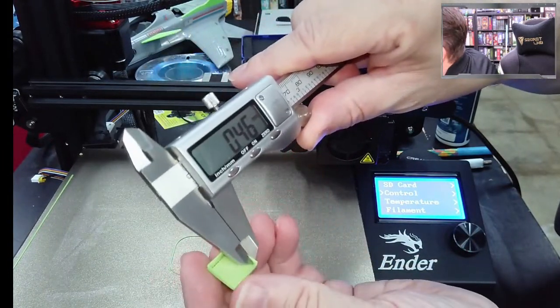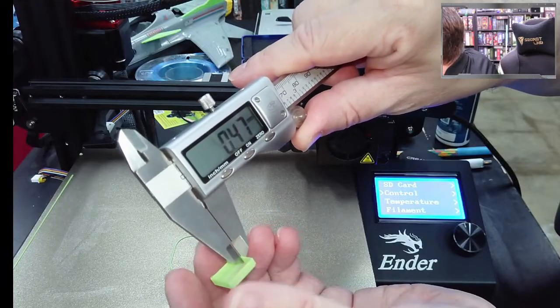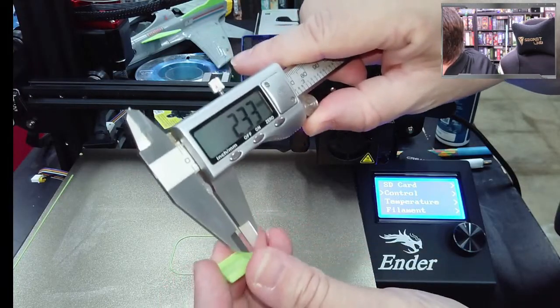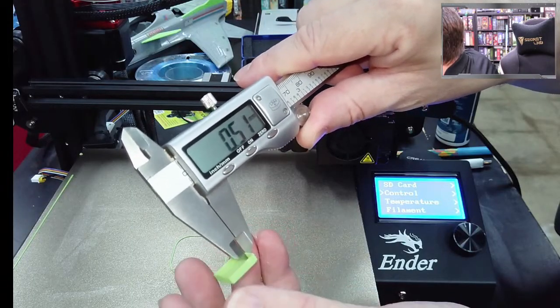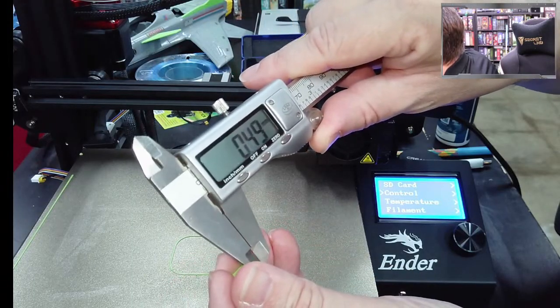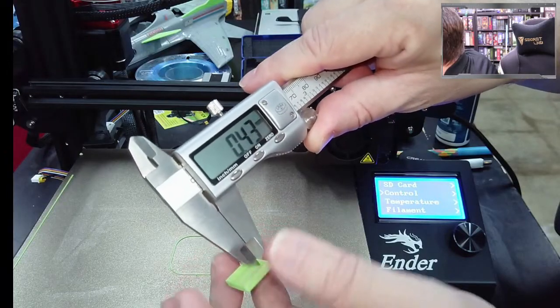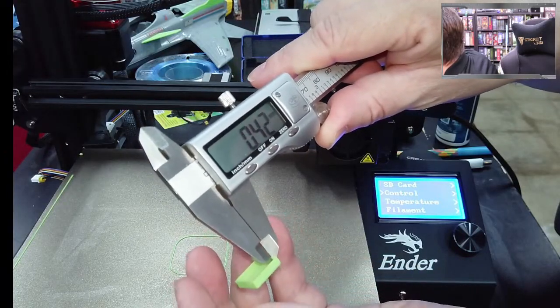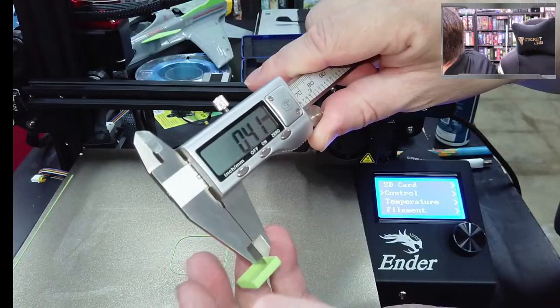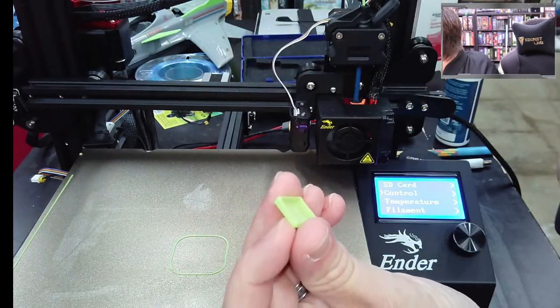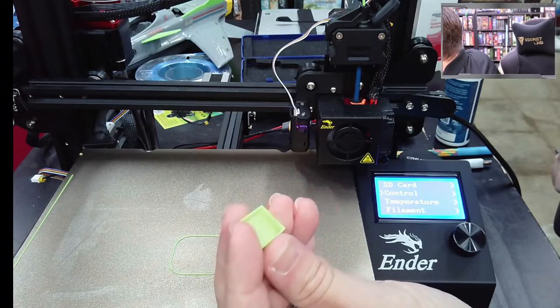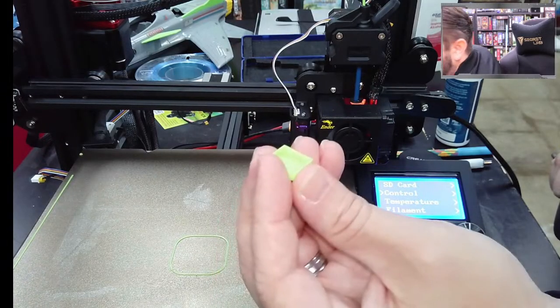So actually this is showing 0.46 here, 0.46 again, 0.56 there, 5.1, 4.9, 4.3, 4.2, and 4.1. So one wall is actually pretty close. The other three are over extruding. So you would go in and average those 8 measurements,